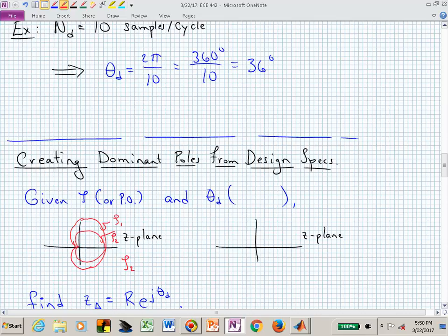So you're not damping at all, are you? It's just continuing to oscillate. So zeta equals 0 is when you're shaking and you don't have any damping. And where are you in the z-plane if you're just shaking, if you're not damping? Or where would you have a pure oscillation for your poles in the z-plane? In the s-plane, it's on the imaginary axis. Where does that map to in the z-plane? It maps to the unit circle.